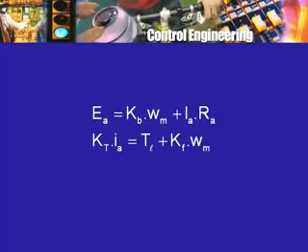So the motor is going to produce more than what the load itself is going to absorb, because some power will be lost in friction. It will appear as heat elsewhere in the bearings, maybe the fan will be turning and so on. So the motor power therefore has to be more than the mechanical power which is to be delivered to the load. And knowing Kf, now how do you know Kf?